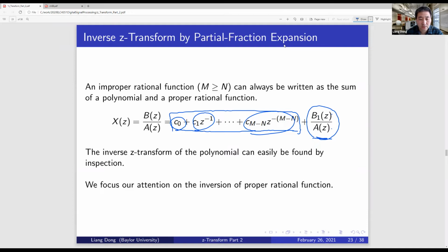And then we know for this constant, it will give me a delta function, just delta n. Inverse Z transform back to time domain. In the Z domain, that's everything. So in the time domain, you have very limited, it's a delta function, delta n. If you work on this term, c1 z to the power -1, we have delta n minus 1. Well, z to the power -k, it's just a delay term. So no surprise, it's very simple.